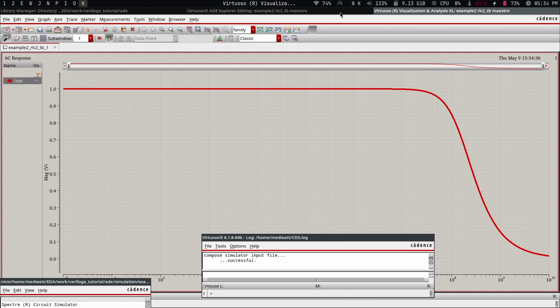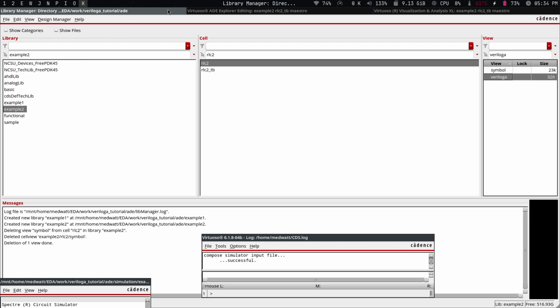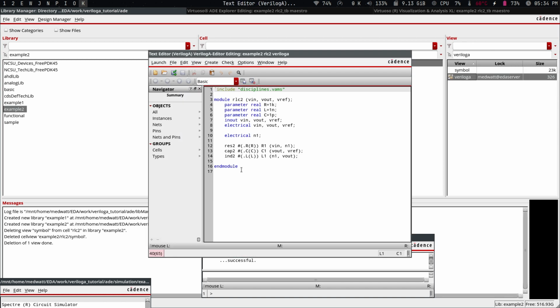This shows you that it's very easy now. Compare this to the previous approach. You can definitely tell that this is way faster. You just bring in your Verilog-A files that you define externally, and then you include these files, and you're done.